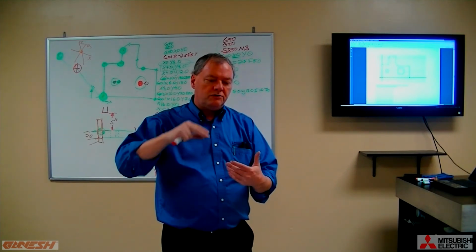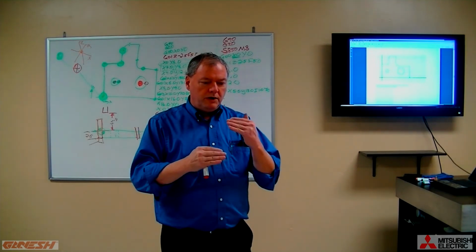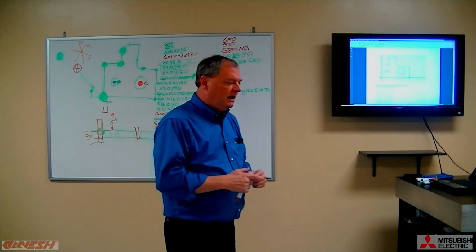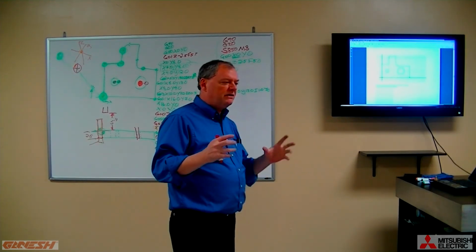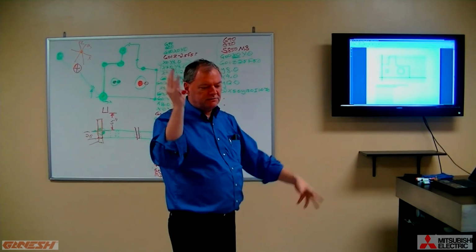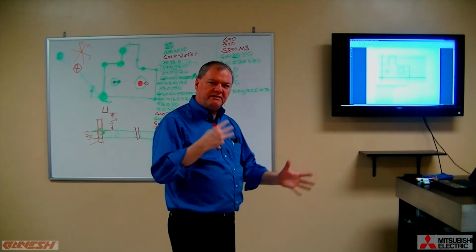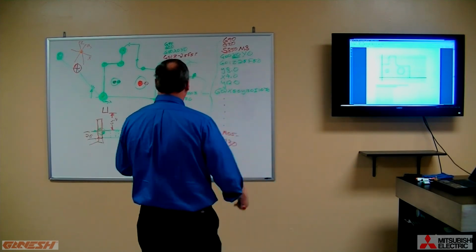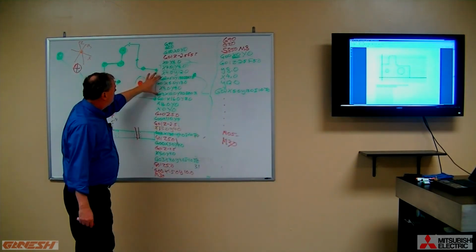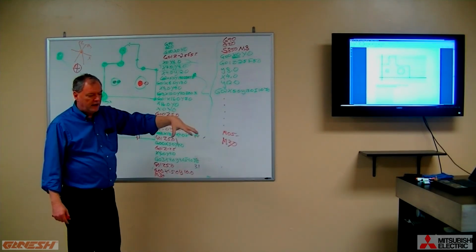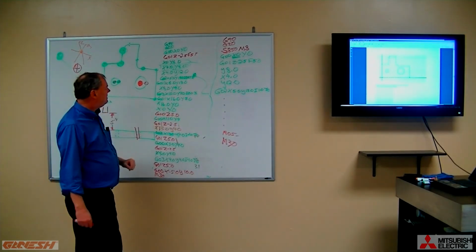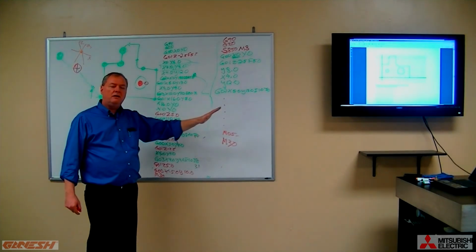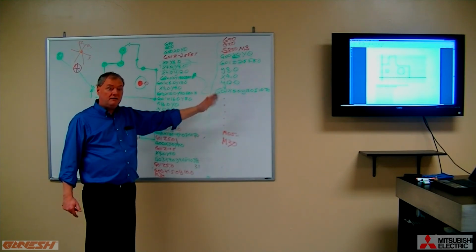And then we're adding codes as we go. So we're assembling a proper program in smaller chunks, in smaller pieces, just to make it a little easier to grasp rather than throwing all of this work holding and spindle speeds and feed rates, all of this up front. Because I want you to really have a good handle on simply making the machine move properly. Rapid, linear, circular, and then worry about the miscellaneous stuff that we need to insert to make it a program for actually cutting some material.